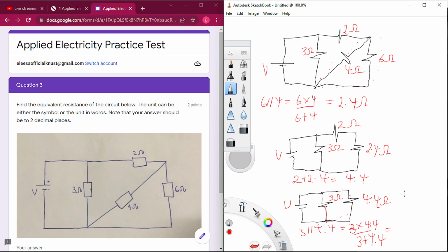So what we realize from here is that this 2 ohm is parallel connected to this 2 ohm and is parallel connected to this 2 ohm. And what we'll do here is to find the effective of these so that we now have just two paths for current to flow through. Realize that 2 parallel 2 is 2 by 2 over 2 plus 2, which is 4 over 4, 1. So we have a new circuit with 1 ohm, 3 ohms, and then 12 volts.